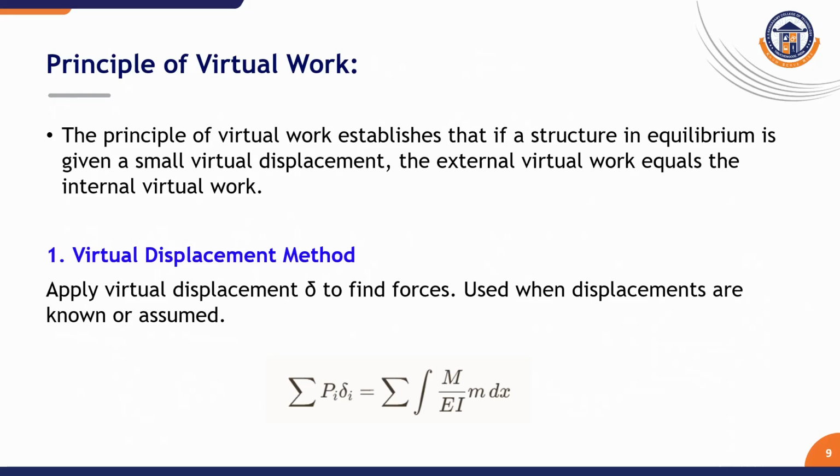Principles of virtual work. Now we come to a very powerful concept, that is, the principle of virtual work. It states that for a structure in equilibrium, the external virtual work equals the internal virtual work. A virtual displacement is imaginary, very small, and consistent with boundary conditions. This principle forms the foundation for many displacement methods. So, virtual displacement and virtual force methods are the basics of the principle of virtual work.